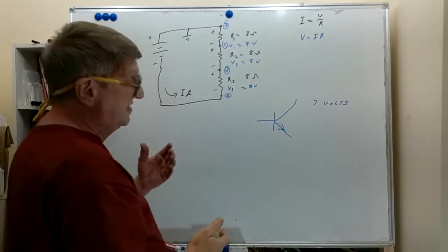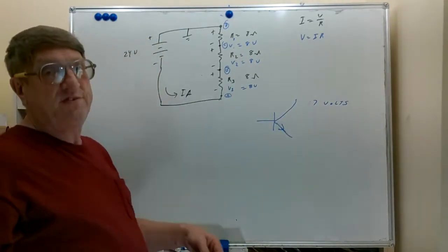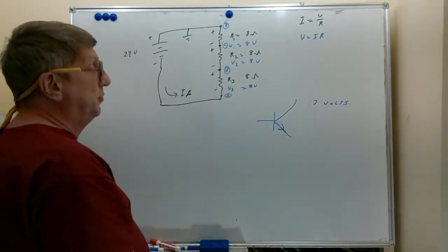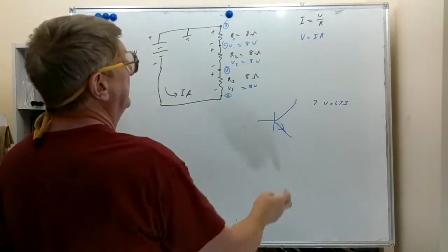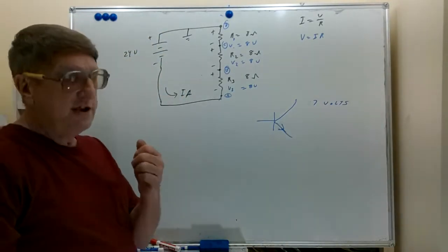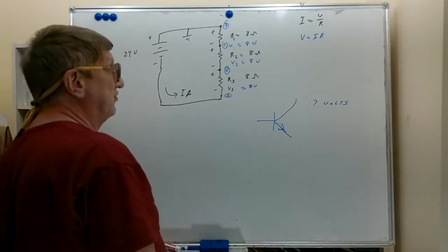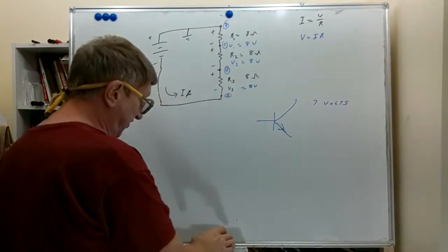So it's basically the voltage drop. You need 2 points to get a potential difference. When you see a single point, it's referenced to ground. So your potential difference is from ground to there, from the chassis to there.